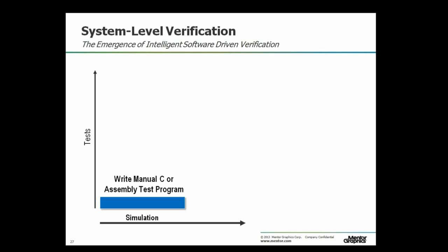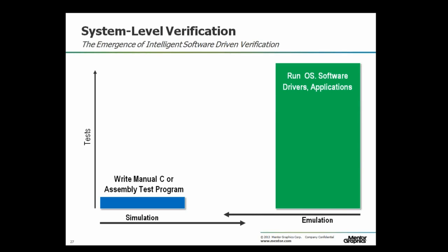So where am I going to find another C or assembly level testbench that I can run against my hardware? And what I can do is look at my own software, my operating system, my drivers, and even the application software. But of course, as we saw earlier, now we're firmly moving into the emulation platform, perhaps even beyond that into hardware prototyping. Now we're running billions and billions of cycles, and our challenge now is how are we going to, for one, run all of them in simulation at speed with the right accuracy, with the right level of diagnostics so that we can actually debug these problems.